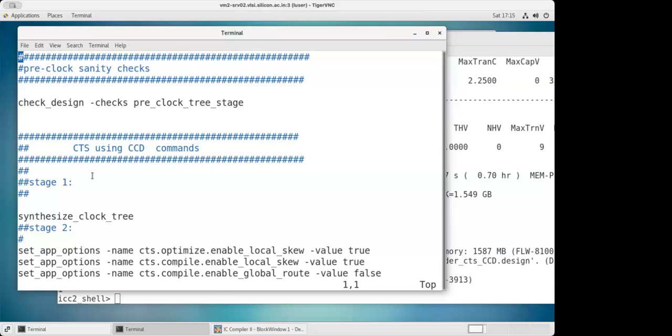So this difference, we measured with the help of a parameter, and that is known as a skew, SKEW, skew. So it is basically the difference between the clock edges which is reaching at a destination. Whatever the time it is going to take, that difference is basically a clock skew.